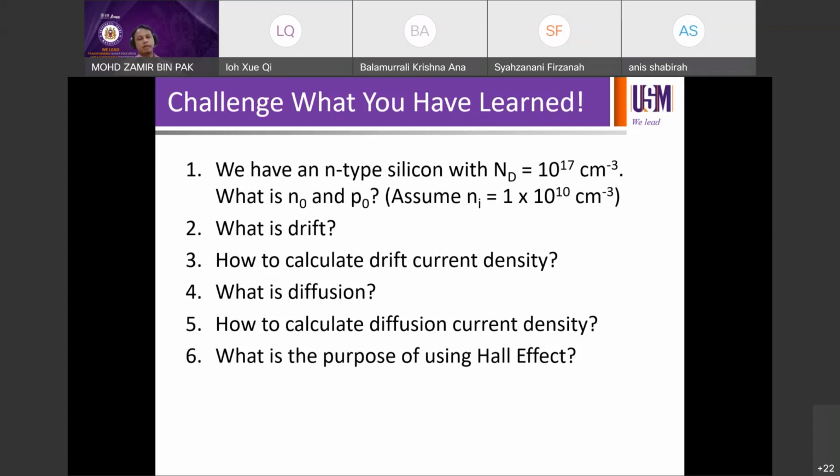Yes. So J equals to NQ mu times E, and your NQ mu will be from the contribution of electrons, where you have to change your mu to mu E, and then your concentration to N, and then the holes will be mu H times the P, right? Change the NQ mu using the concentration of your holes, right? So it'll be contributed by both components depending on the carrier concentration, of course.